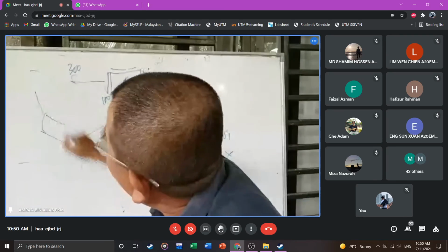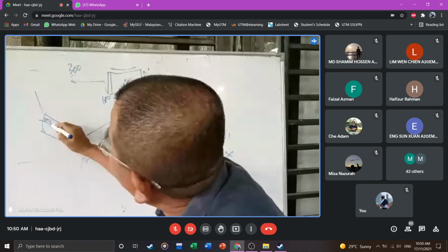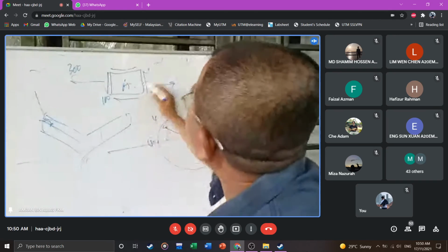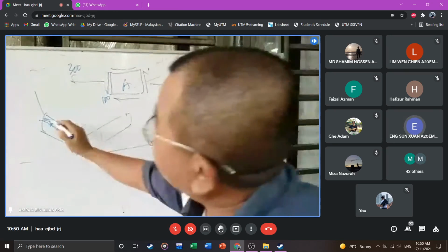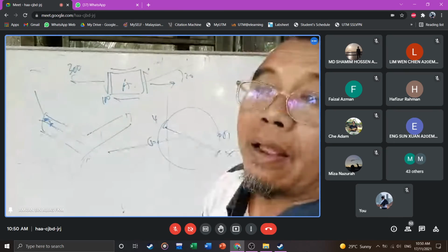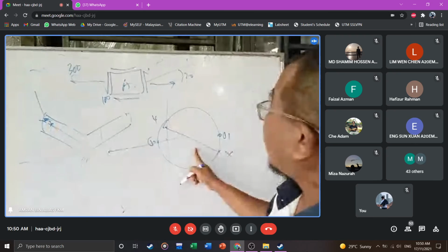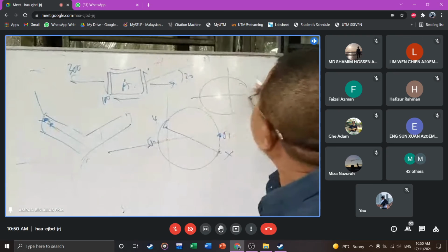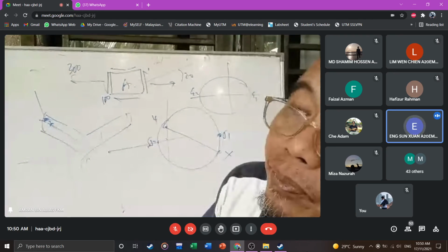says I put a strain gauge here at an angle of 30 degrees to that axis. So that axis for A is 30 degrees from that axis. You see that? Yes. What is the value of strain here? This is stress analysis, but you want to find the strain. So what do we do there? Convert sigma 1 and sigma 2 to epsilon 1 and epsilon 2. Are you with me? Yes.